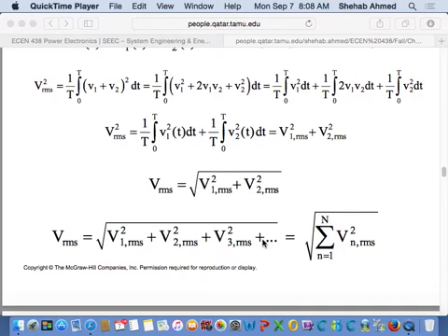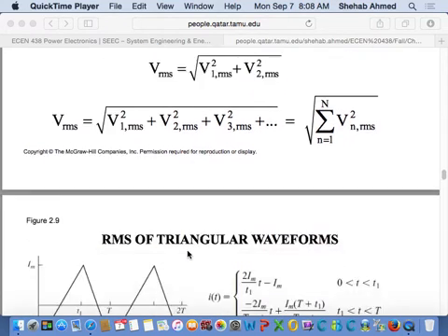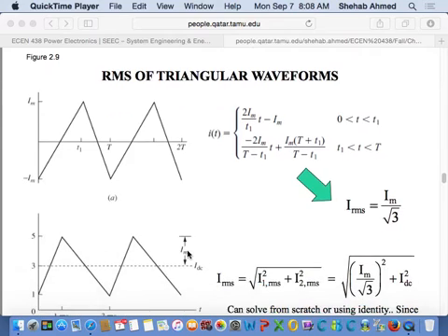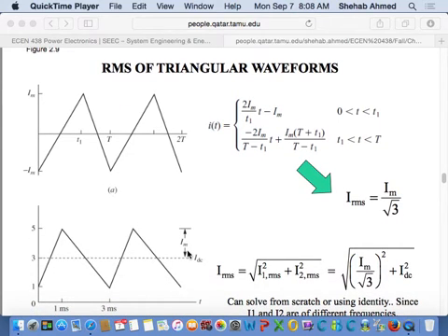From the Fourier transform or Fourier series, you will be able to get the equations for the RMS values, or the peak values, of the individual components that make up this periodic waveform. So if you have the Fourier series expansion of a waveform, you should be able to find the RMS value of that final waveform using this identity that we came up with. And it's also very practical and very useful when we talk about DC power supplies.